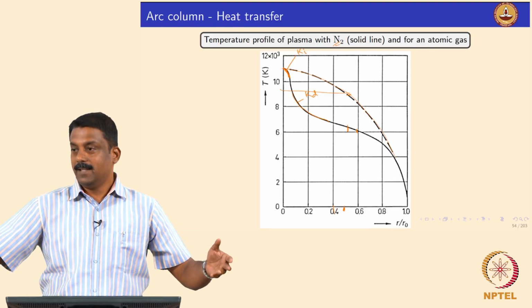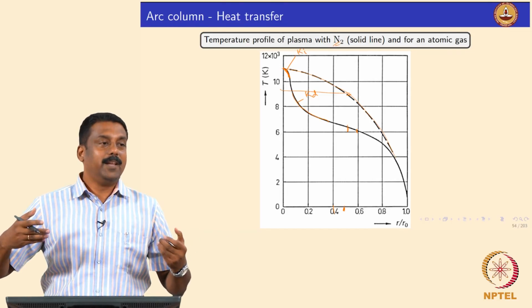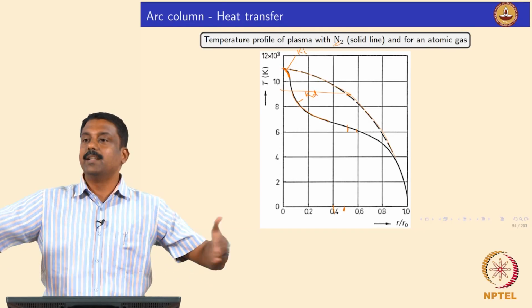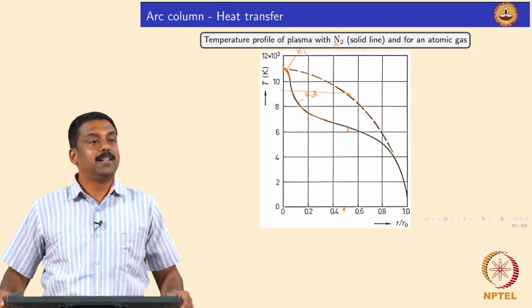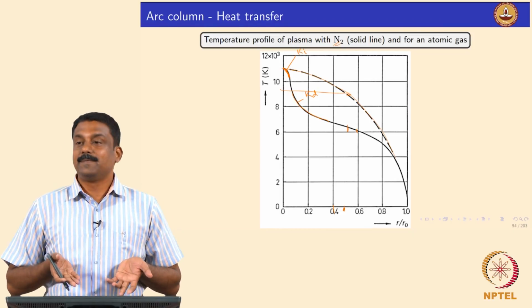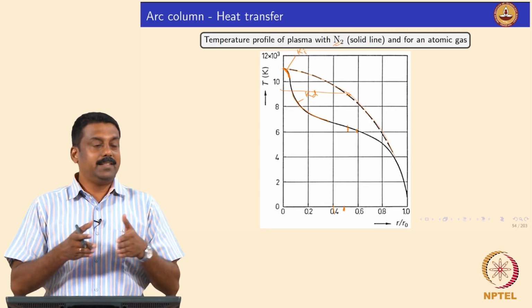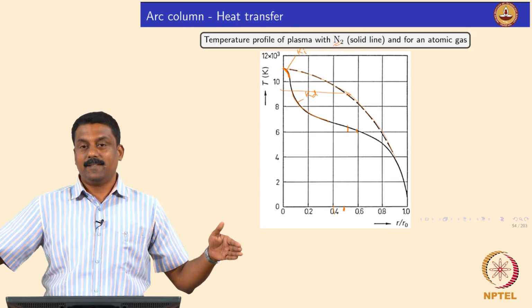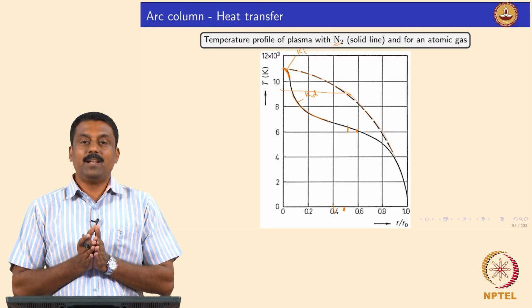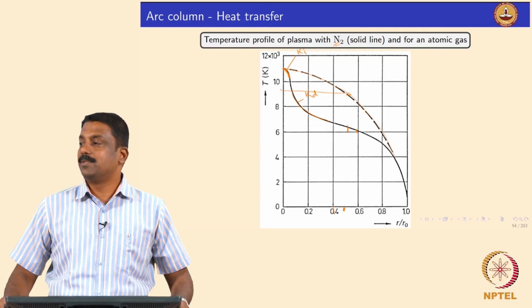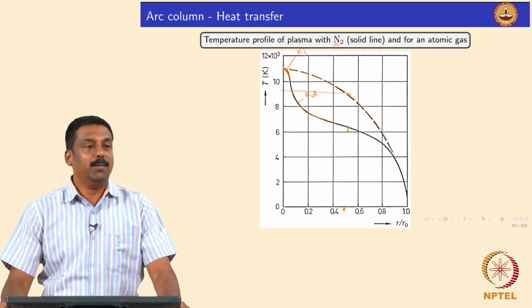to other place. So, that means that if you want to reduce the penetration and if you want to make the weld bead wider, so obviously you can use diatomic gas, isn't it? Because heat is distributed much more widely, whereas if you use monatomic argon or helium, you have a deeper penetration, but a narrow weld pool.